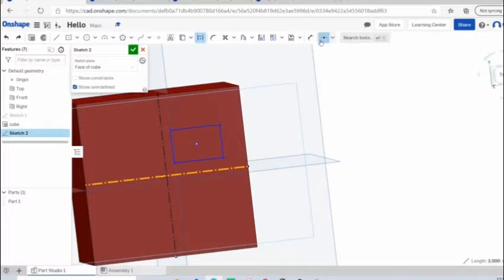So once again, after we draw that center point rectangle, we'll use the midpoint function. Just click on one of these two lines. It really doesn't matter. Technically, you could just use one of the lines as long as you're careful to use that midpoint function. There are also other ways of doing this, like going up to a point and making these two coincident. But I just decided that we might as well do this.